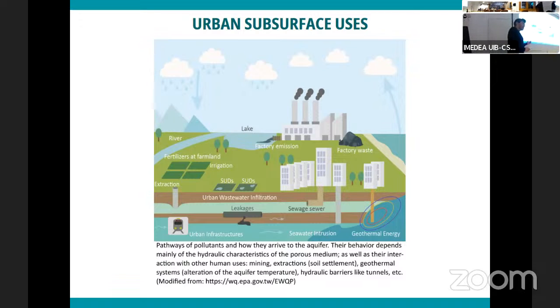If we extract this water, mostly close to the sea, we make seawater go inland and increase seawater intrusion. The problem is that this puts more salinity in the groundwater, so sometimes we say that this water is contaminated by saltwater. We cannot use it directly for irrigation or drinking. We have to do some treatments before using it.